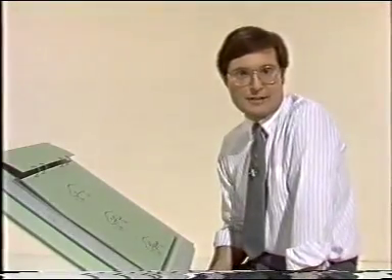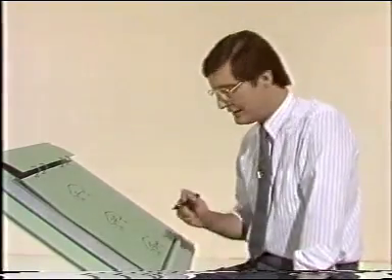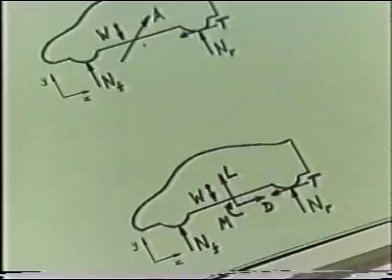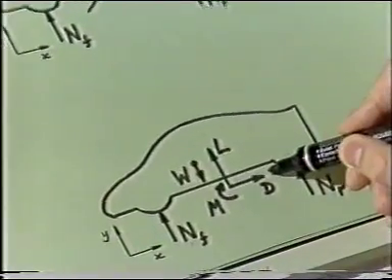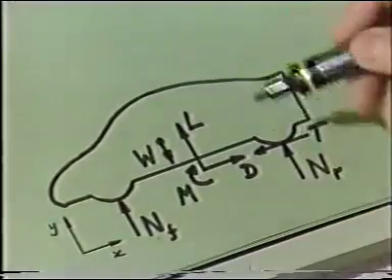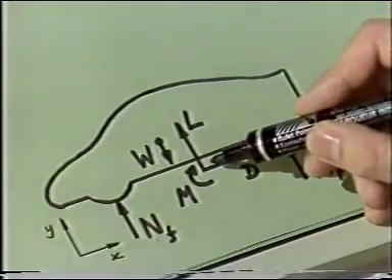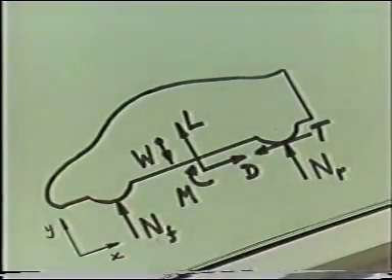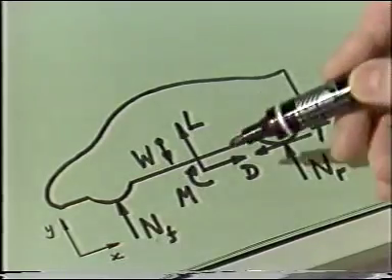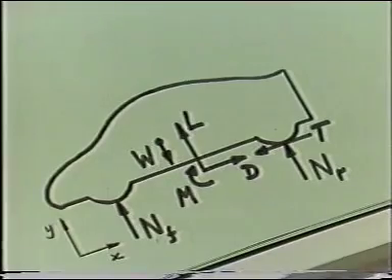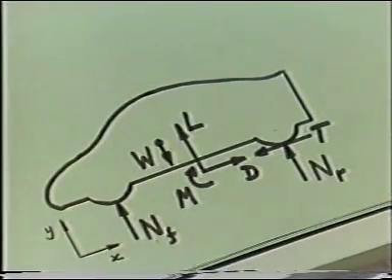Now that representation isn't very convenient for analysis, so the usual thing to do is to take an aerodynamic origin here at ground level and to consider the force in components. So there is a horizontal component, the drag force D, a vertical component, the lift force L, and a pitching moment M, considered about this point. Knowing D, L, M and W, from this free body diagram we could use equilibrium to find NF, NR and T. I've shown L as upwards here, and most cars do have some lift, although racing cars are designed to have a big down force, because this increases the tyre vertical reactions, giving more grip.